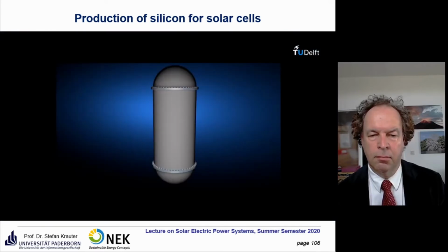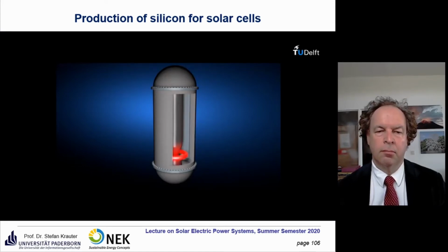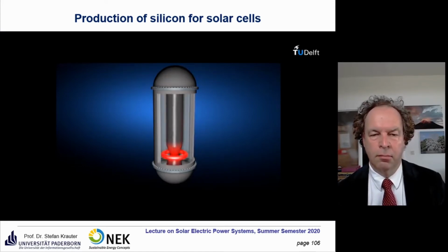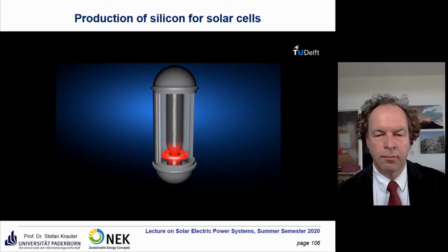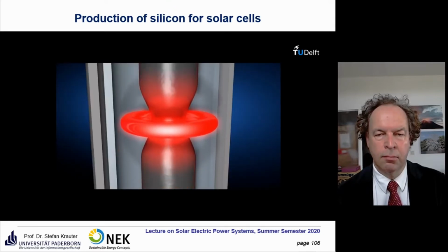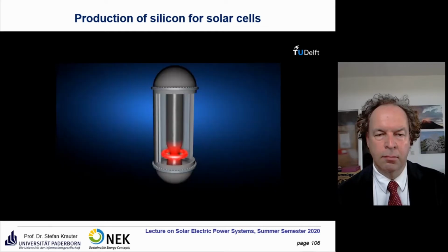The source material is a polycrystalline rod as processed in the earlier mentioned Siemens process. The end of the rod is heated up and melted using a radiofrequency heating coil. The melted part is put in contact with a seed crystal. Here it solidifies again and adopts the orientation of the seed crystal. Again, both 100 and 111 orientations are being used. As the molten zone is moved along the polysilicon rod, the single crystal ingot is growing as well. Many impurities remain in and move along with the molten zone.